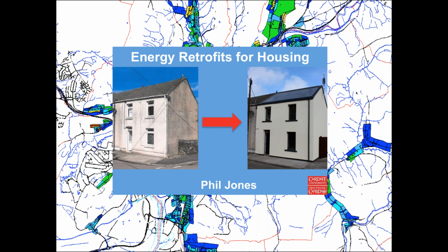What are your thoughts? None of the houses that we've retrofitted have any cooling system, and I think most of them would, especially the solid wall construction with the external wall insulation, would probably not have any cooling requirements. I understand, of course, that new build, especially lightweight construction with poor ventilation, often has summertime overheating. The mechanical ventilation heat recovery also helps with this, so it ensures that there is good ventilation in the summer as well. So I appreciate it could be a problem for new build, but not for retrofit. And we've monitored a number of these houses, and we haven't had any issues of overheating.